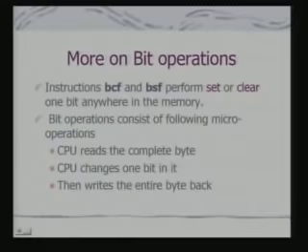So, we shall discuss this problem when we actually discuss the peripherals, that is, the digital I/O ports which are supported on PIC. But this read, modify, write is again an atomic operation. The advantage of the atomic operation is this cannot be interrupted by an external interrupt.